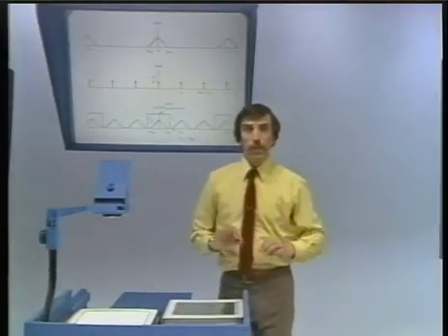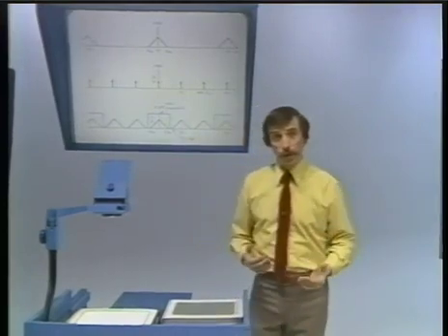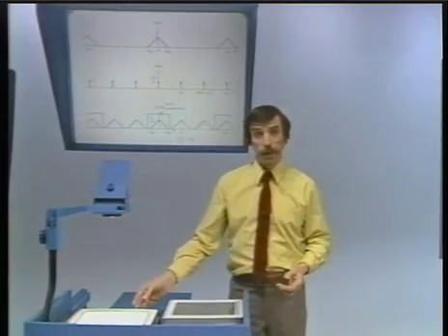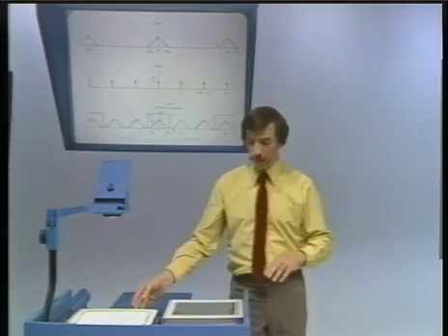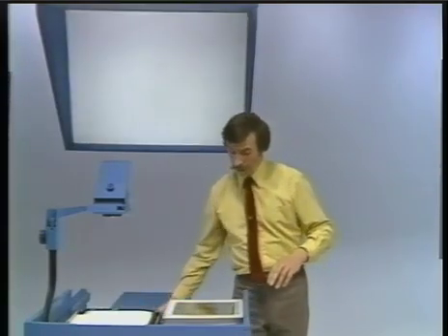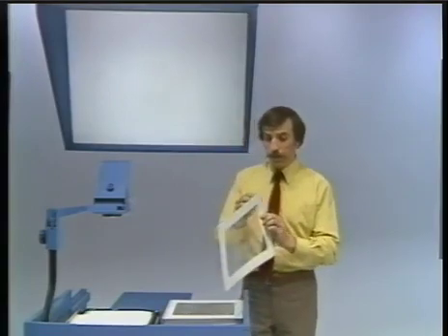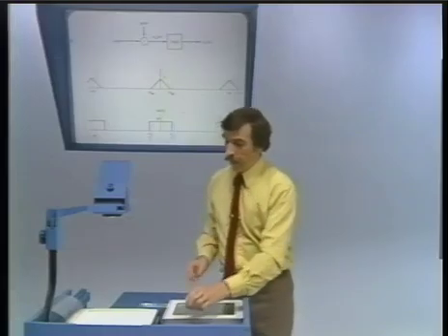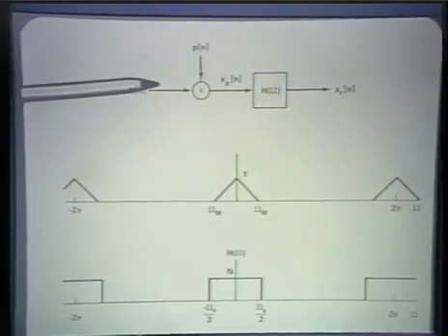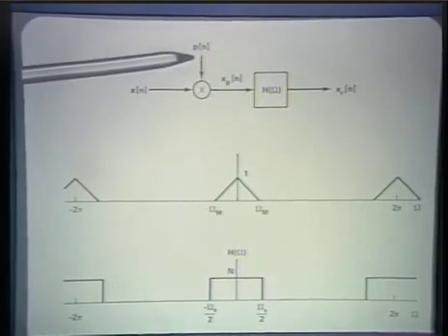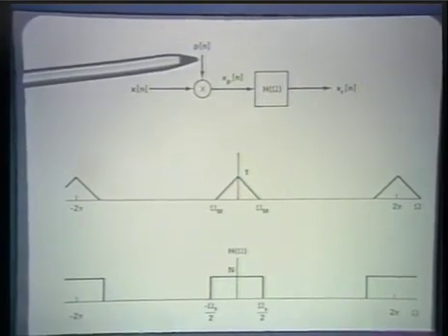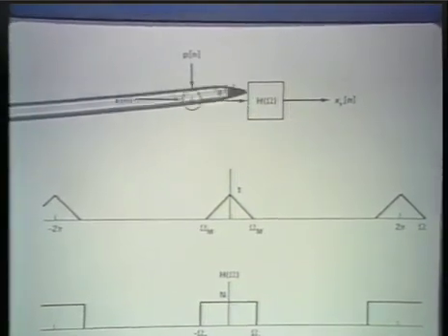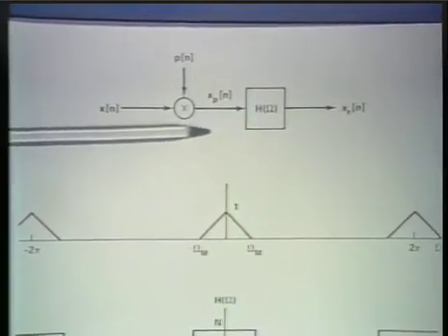So what we see, again, is that the process is very much the same. As long as there's no aliasing, we can recover the original signal by ideal low-pass filtering. So the overall system is, just to reiterate, a system which consists of modulating the original sequence with a pulse train or impulse train, and then that is going to be processed with a low-pass filter.